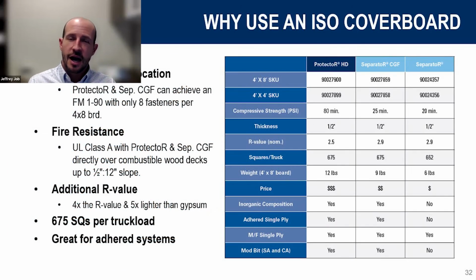Some of the key highlights are going to be, of course, impact resistance, whether it be people walking on the roof, hail impact, service maintenance, or maybe solar array type applications, and how that's going to support or protect that insulation package below. Because if we start compressing that insulation, puncturing it, damaging it, then we've lost the thermal performance of what we paid for. So call it an insurance component package to add to that system.